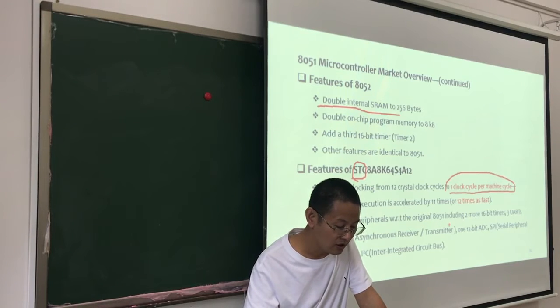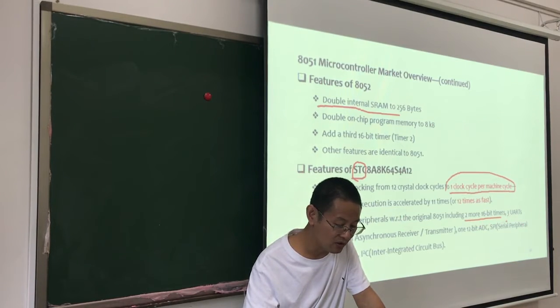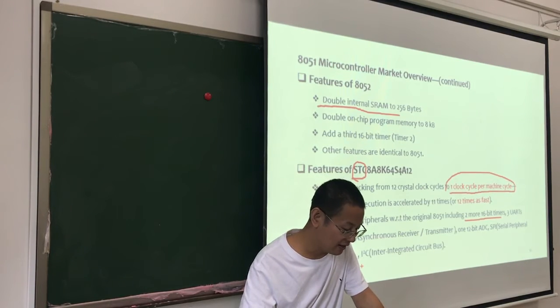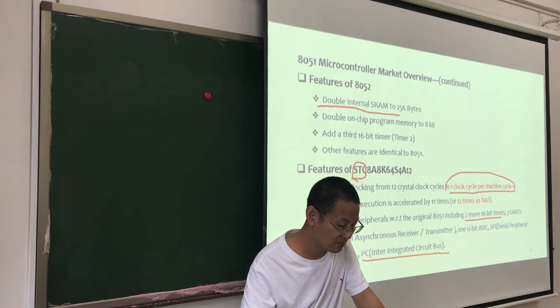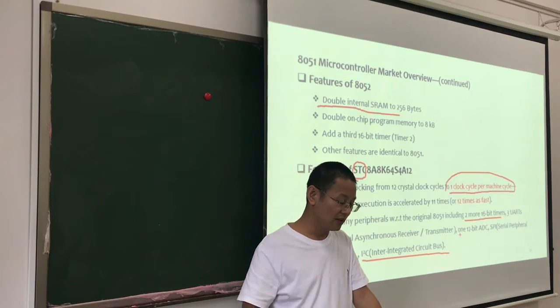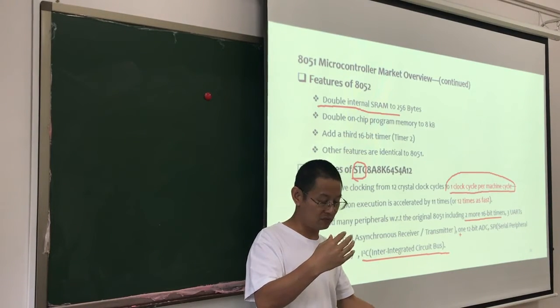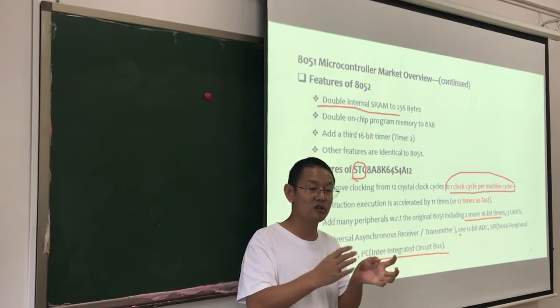The original 8051 includes two timers, but the STC microcontroller may include more: more timers, more UARTs, and even ADC, SPI, and I2C. The STC microcontroller integrates many peripherals into the chip.